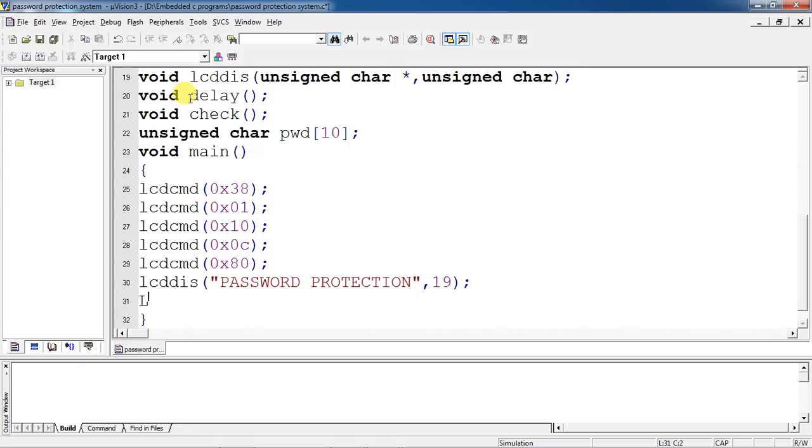And if you are looking to go to the second line with the 20x4, you should pass the LCD command 0x94. To pass the second line, this is 0xC0.